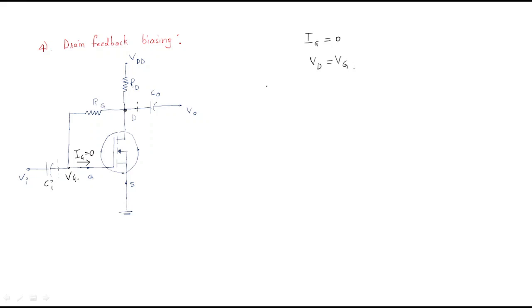Okay, so can I elaborate on this? This VDS voltage and VGS voltage are both the same. So I will write that the drain-source voltage and the gate-source voltage are both the same. From this, we remove this drop. VDS is the supply voltage minus this drop, so VDS or VGS is VDD minus ID RD.